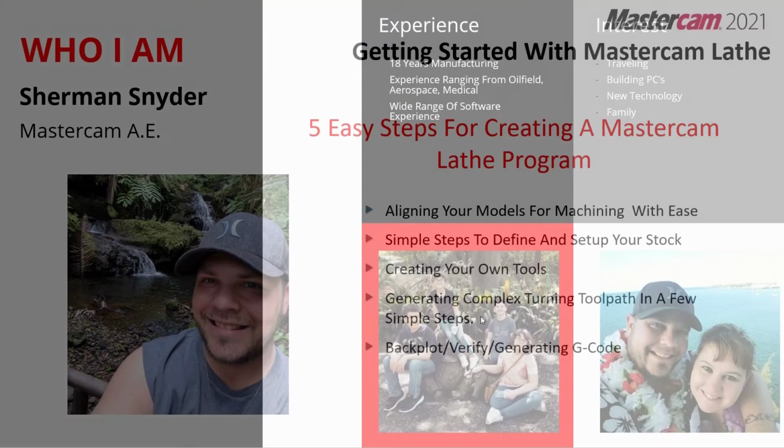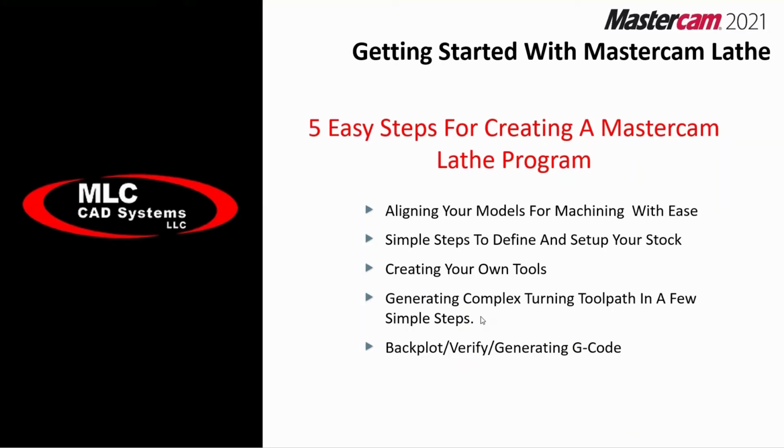But let's go ahead and jump along. For this Cam Skills event, getting started with Mastercam Lathe, I'm going to talk about 5 easy steps for creating a Mastercam Lathe program. We'll start off with aligning our model and machining with ease. Simple steps to define and set up your stock as well. Creating your own tools, and there's going to be a couple interesting things I'll talk about in that as well. Generating complex toolpaths in just a few easy steps, and then what everybody comes to any kind of CAM software for: backplot, verify, and generating G-code, which is pretty much the main thing that we're looking for.